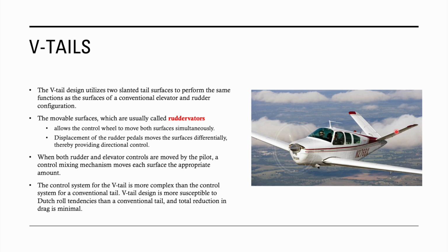So depending on the flight controls or your control input, it's able to tell whether you're just trying to use elevator by pitching, if you're also introducing your rudder pedals, and it's going to control the amount of deflection depending on what controls you're putting in.